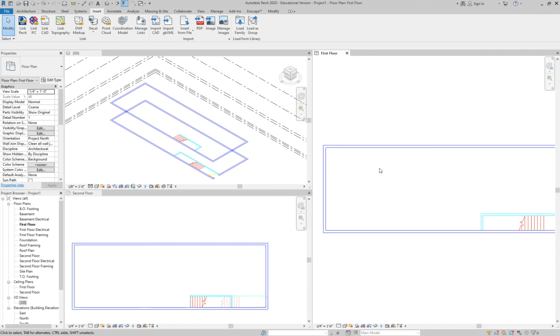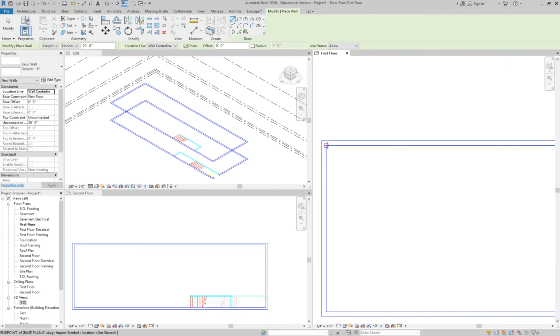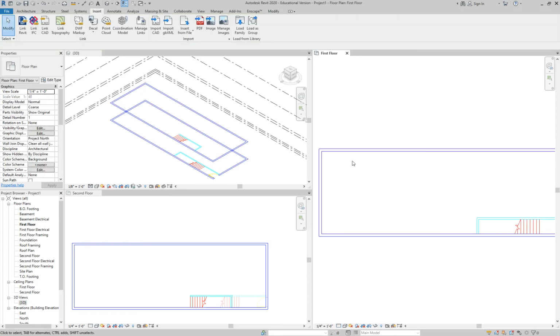3D view, because 3D is obvious, if I was new at this and I didn't know how to tile windows, how could I know if my walls were right or not? Change your view to detail. Fine or medium. Yeah, change your view settings to medium or fine so you can see those lines of the details to see where they're going. Good. So let me hop in here and let's do this.